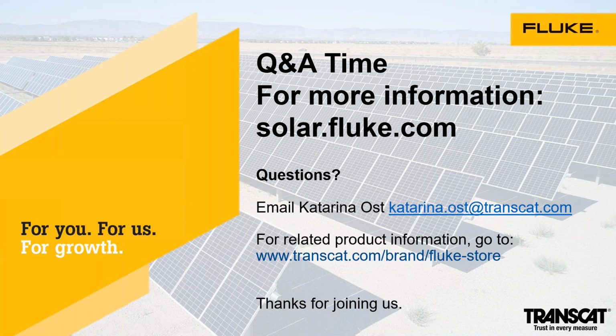If you see the torque marks on there, assuming that they did the torquing right in the first place, that would be pretty good. I personally would go through and retorque everything. Most inverter or equipment manufacturers are going to give you some type of indication of how often they need to be retorqued.